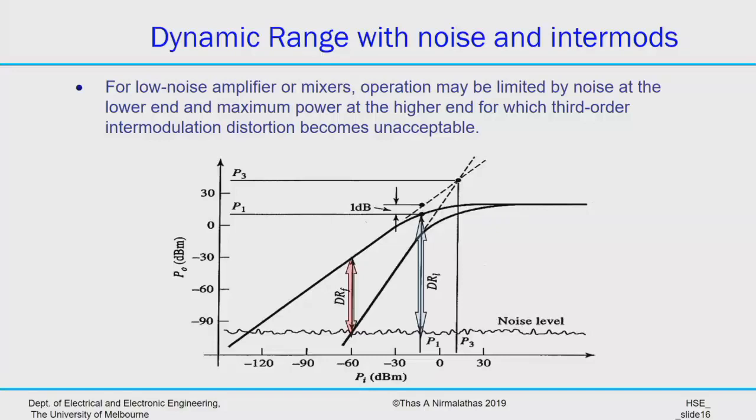One is here where the intermodulation is almost the same as the noise and the signal can operate up to that point, all right? That is one kind of dynamic range we can mention. That means we don't want any intermodulation at all. Or we can say we tolerate some amount of intermodulation, but we are well above the noise and the 1 dB compression. This is your linear dynamic range. And so we wanted to define a further kind of measurement in order to include the intermodulation distortion in our characteristics.